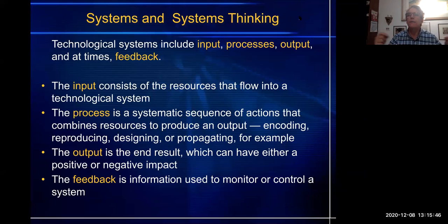I am the one that has to adjust the system if it's putting out too much or too little, or the toast didn't turn out right. Open loops need a human. Closed loops have something like a thermometer that is measuring the output of the system and providing feedback back into the system. So let's think about my heating system.